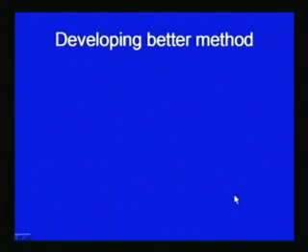Now, after carrying out the work measurement, we will be able to see the presence of ineffective time in the existing method, and the presence of any ineffective time and its extent in the existing method will provide the avenues for developing the new method and for improving the existing method. Improvement of the existing method and development of the new method is carried out effectively after work measurement,